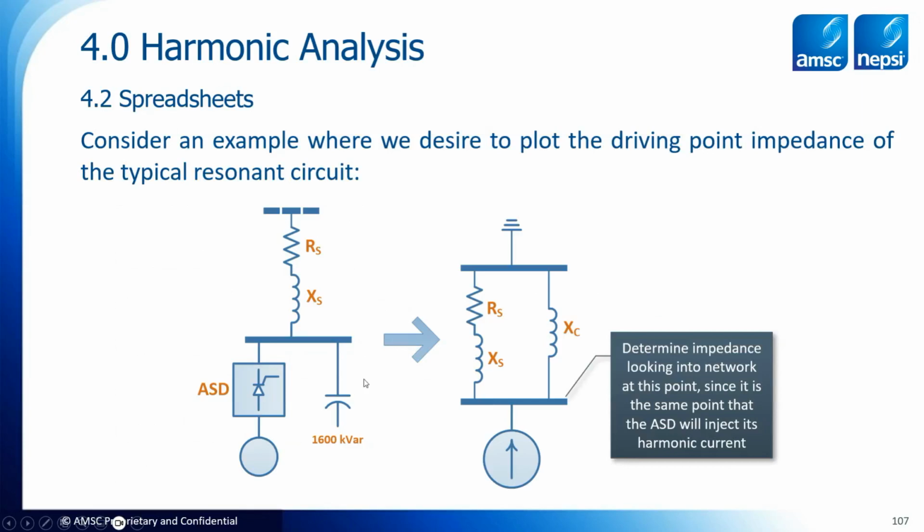This might take some explanation in a later webinar as to why this is true, but just understand that from a harmonic perspective and from a three-phase balanced perspective, this source impedance to the grid gets shorted to what's called the reference bus. And that is also true for this ungrounded Y capacitor bank. In the three-phase balance sense, it goes to what's called the reference bus. So these components are actually in parallel.